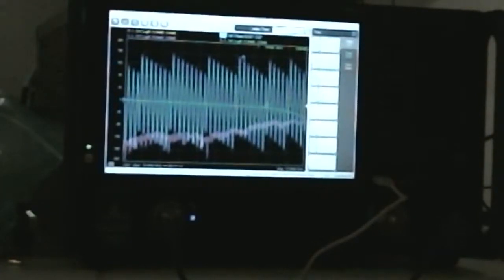So it will not, and I can show you. We can do a 1-port calibration with this, and I can measure the return loss of the network analyzer just of itself. Bend the cable, come back, and I'll measure a completely different return loss. The magnitude might be similar, it might be very close. It also depends on the accuracy, right? So let's be honest here.